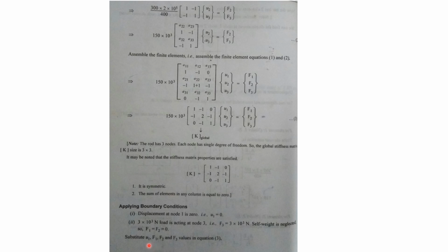So substituting u1, F1, F2 and F3 values in equation number 3. After substituting the boundary conditions, we will get this equation. u1 became 0, u2 and u3 are the unknowns. We have to find that F1, F2 are 0, F3 is 3 into 10 raised to 3. Now we have to solve for u2 and u3. So there is a simple method for solving this